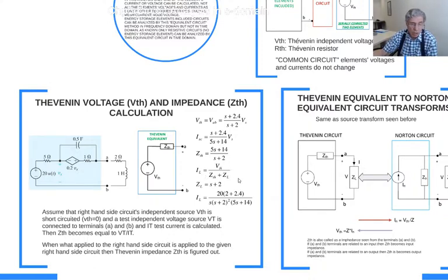So what is the advantage of this? We said if you change your load for any load, this formula stays as it is. That means you are not going to recalculate Thevenin voltage and impedance in here. That is the advantage. Now let's go in how we are going to find out VTH and ZTH in this example.